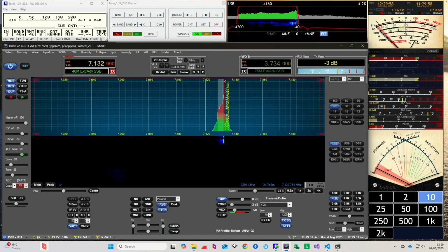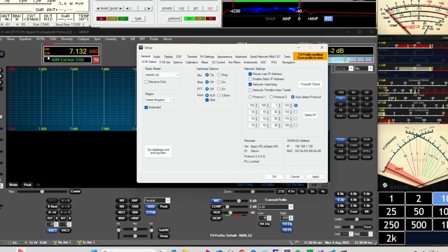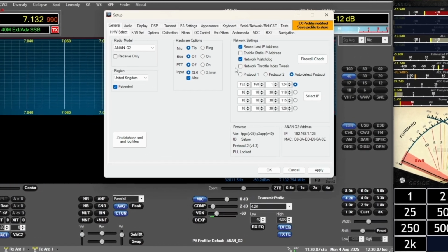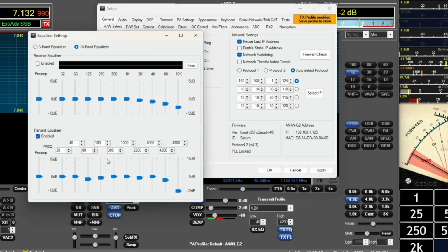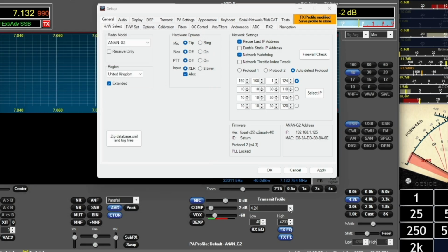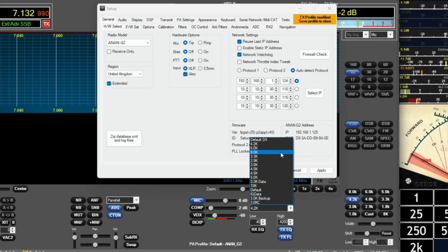Now we're in the radio, so you're listening to my audio now as is coming from the monitor, and in here there are various other settings. So actually the first setting to note is I'm on a 4.2 kilohertz transmission bandwidth, and I am doing some extra equalization. Depending on which transmission bandwidth I'm using, I'm just tweaking this slightly because I've EQ'd the Apollo system for wideband 8 kilohertz. So let me go for 8K.